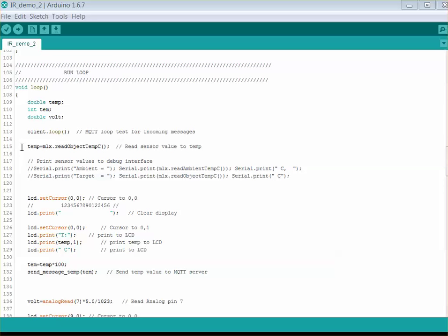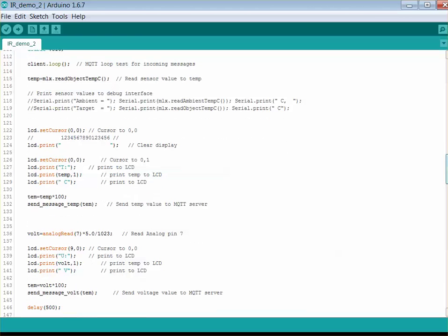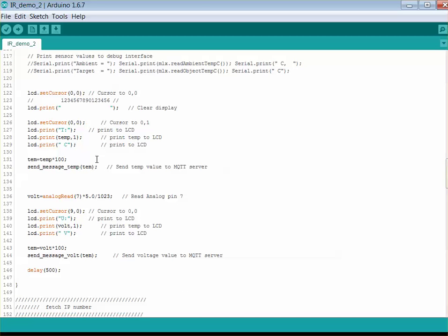And here we are reading a temperature value. This is quite a simple way. We only call the sensor library function and it gives us the temperature. Then we put cursors to define the display places where to start printing these numbers, and here we print T as temperature, the variable containing the temperature value, and C as Celsius.